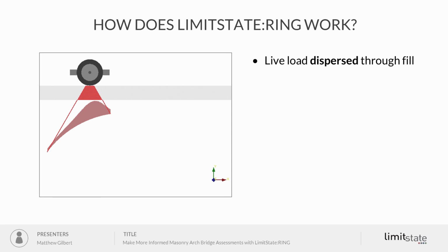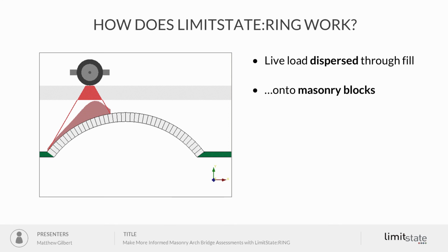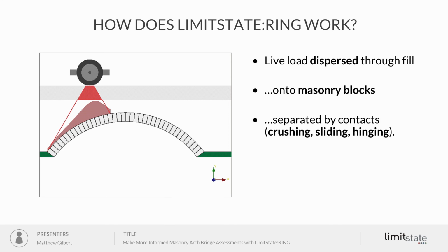So how does it work? The load from vehicles is dispersed through the fill onto blocks, which are separated by contacts, which is actually where the interesting stuff happens. We model the crushing, sliding and hinging behaviour there.